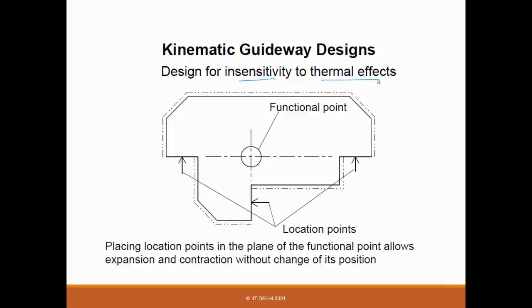In high precision and ultra precision systems, that is not desirable. First thing is, you want to avoid any thermal centers or heat sources, or if you have them, you try to make a way that the heat dissipates easily. That's why we talk about the thermal loop, right?